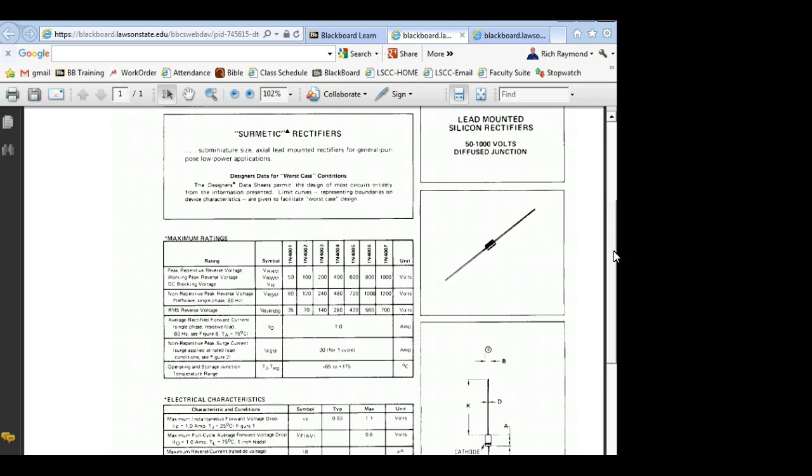And we'll look at the PIV when we start playing around with next class, when we start looking at full wave rectifiers and charging up the capacitor, charging up that filter. You're going to have to figure out that PIV or that reverse breakover rating on the diode, because it's sometimes actually over peak, and we'll have to look at that. So we okay?